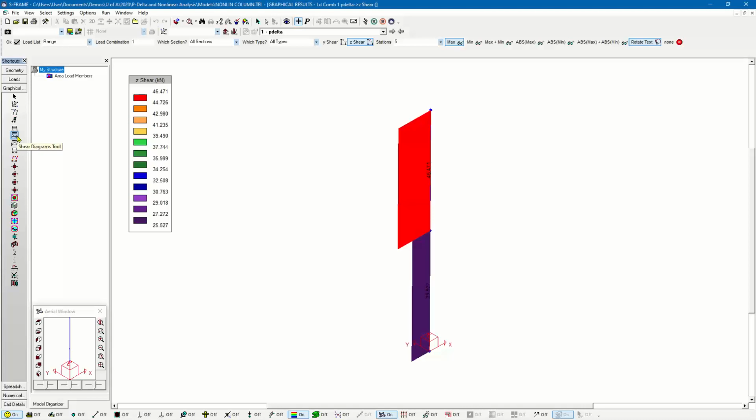This wouldn't happen in the actual, what am I trying to say? The P-Delta static analysis. So that, along with the geometry that we're getting and updating throughout the analysis, actually leads us to slightly smaller deflections than what we calculated with the P-Delta buckling or static analysis.